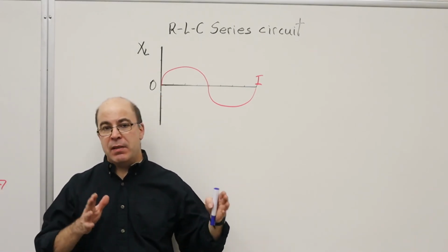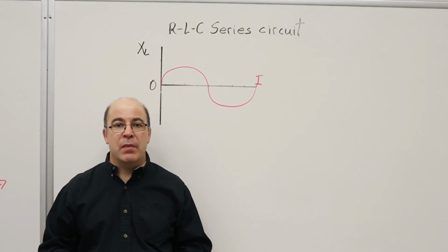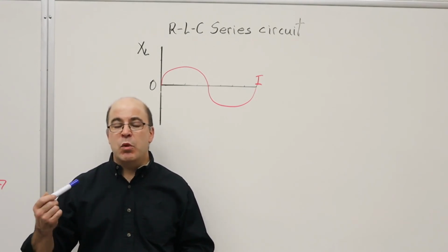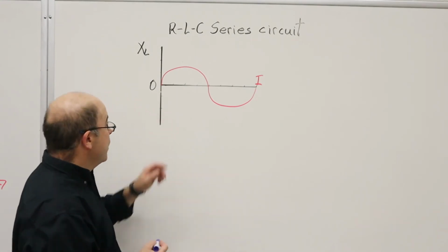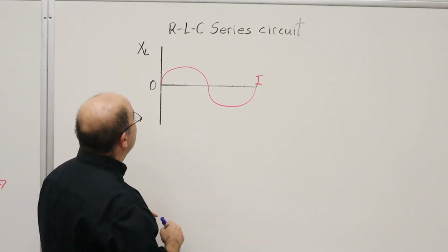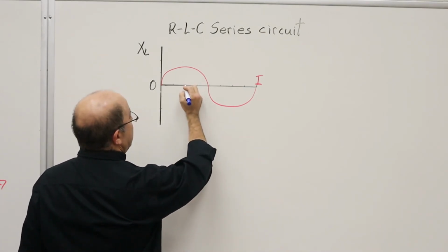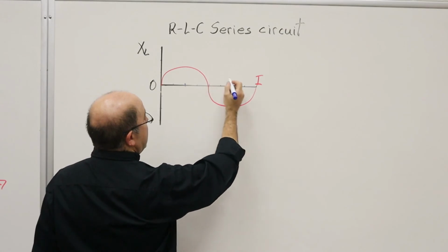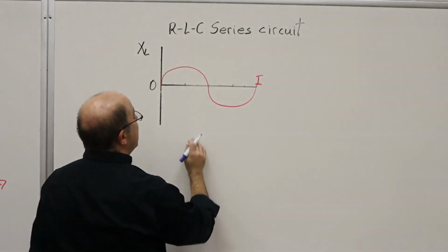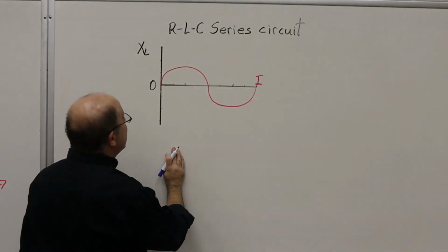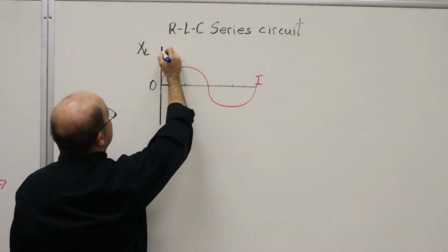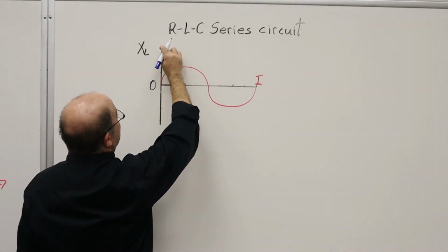It becomes a stationary waveform that all others move in relation to. As such, here's our 90 degrees. There's 180, 270, and 360. And the voltage is leading. So that means then that the waveform is going to start up here.